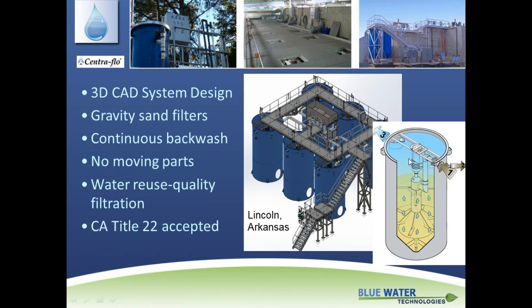There's a wash box that sits within the center portion of the vessel. This wash box is for recirculating and cleaning the media and for scrubbing the spent absorptive coating off the media. So again, this happens continuously, where the airlift will actually lift the spent media from the bottom of the vessel where it's dirtiest, carry it to the top of the vessel, discharge to the wash box, where it'll fall through a baffle.